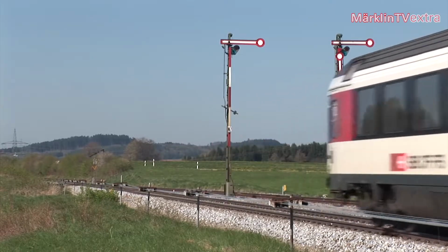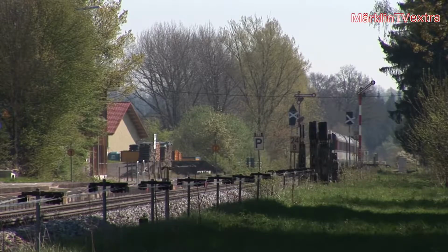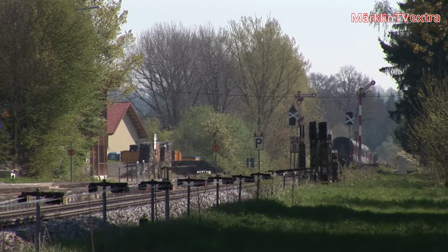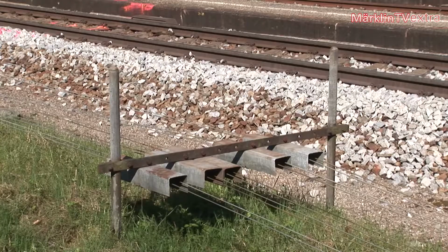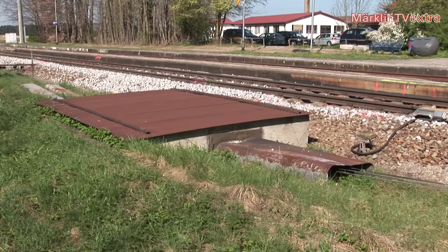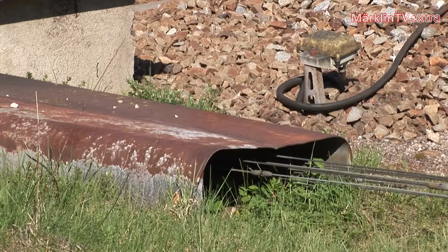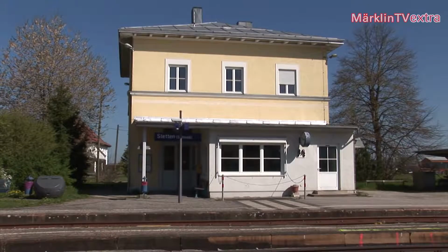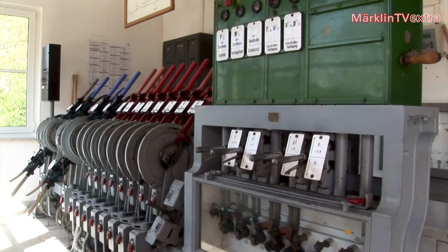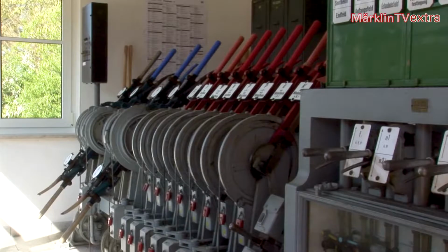Semaphores are part of the mechanical interlocking tower. Both turnouts and signals are controlled with the help of wires. If you want to recreate this operating mechanism in detail, you will find matching components for sale at the various accessory suppliers. It takes some skill to accomplish the reproduction. In contrast, counterweights are available ready to use. Pictured here is a lever frame with turnout and signal levers. It takes a strong arm to operate the levers.